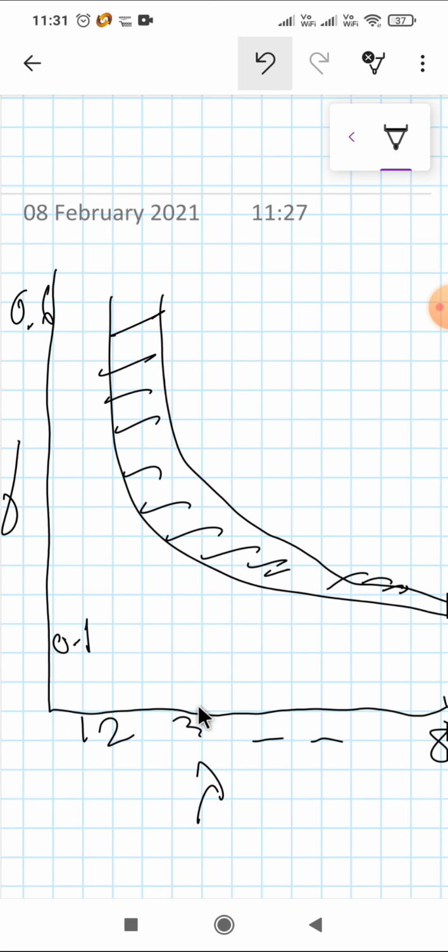Here we can see that as tip speed ratio is increasing, the solidity is reducing. Similarly, if tip speed ratio is reducing, the solidity is increasing. If 2 to 3 blade rotors are there, then the solidity is very low. If more blades are there, then solidity will increase.